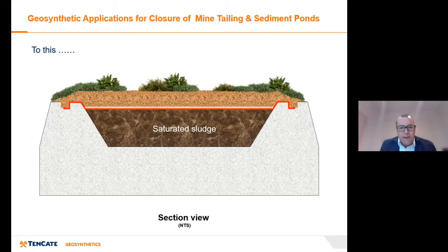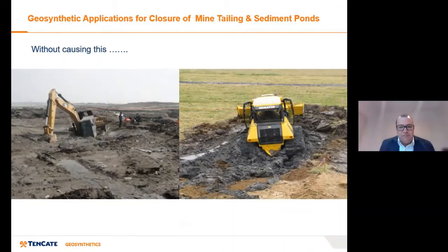So we want to get to this solution without this happening, where you think you're building on top of a stiff crust, or on top of drier tailings, or drier sludge than is actually there. And of course, what happens is you break through the crust, and then you find yourself in trouble with machinery or people starting to sink down. So that's what we don't want to happen.